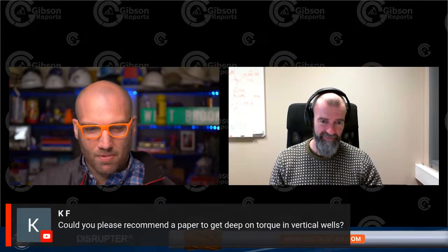And then if you have a wear result, you can take those wear grooves as a percentage value and insert that into your casing analysis, and then you get new numbers out, and you would see whether or not you could satisfy the government. Is this good enough for maintaining control of the well? There you go. All right.